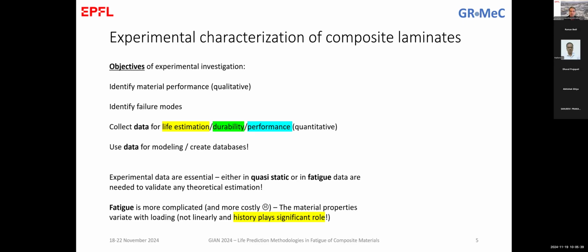In other cases, we need to know if the material will stay there under different environmental conditions. This is in structures that work outside, in what we call the open air. It is important to know if the structures can survive under higher temperatures, when we have wet environments, when we go to very, very low temperatures that in several cases are more critical than high temperatures. And there we talk about the durability of the materials. In this case, we need to perform additional testing. It's not only a life under certain load, but it can be life under certain load at different temperatures. It might be life under certain load at different temperatures and different frequencies. So there you see, every time that we add a parameter, we add to the complexity of the testing.